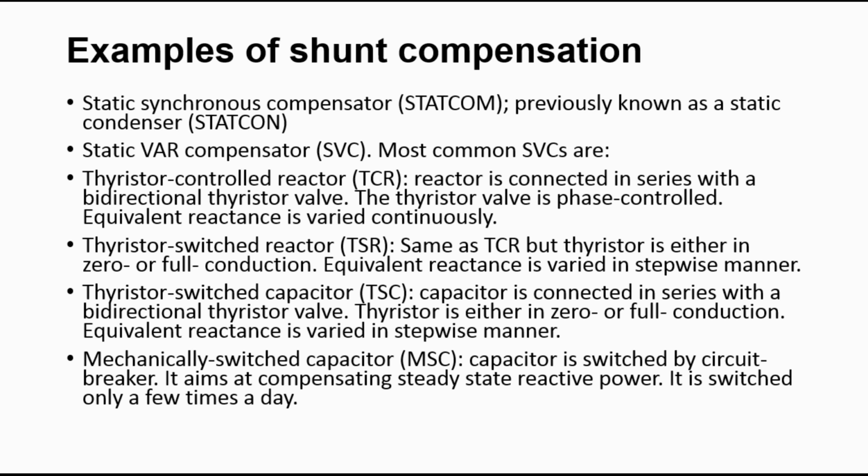Mechanically switched capacitor, MSC, the capacitor is switched by a circuit breaker. It aims at compensating steady-state reactive power. It is switched only a few times a day.